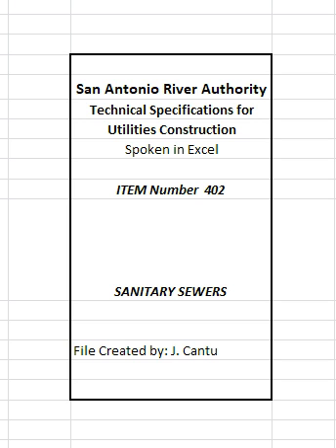Sand interceptors. Sand interceptors shall be installed in the sewer system of the following establishments: garages, car washes, service stations, or any place of business where heavy solids may be introduced into the sanitary sewer system.